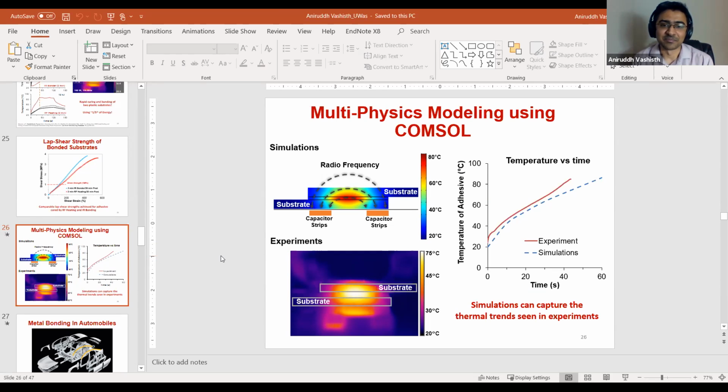Yeah, so this is actually a very difficult process. My appreciation for simulation went up when I was working with the electrical engineer who was doing these simulations. There are a bunch of factors that go into the simulation. The first factor itself is what frequency you're using as the input frequency for these types of applicators. The way we were making the applicators was that we would just use our hands to lay out two copper strips and put Teflon tape on top of it.